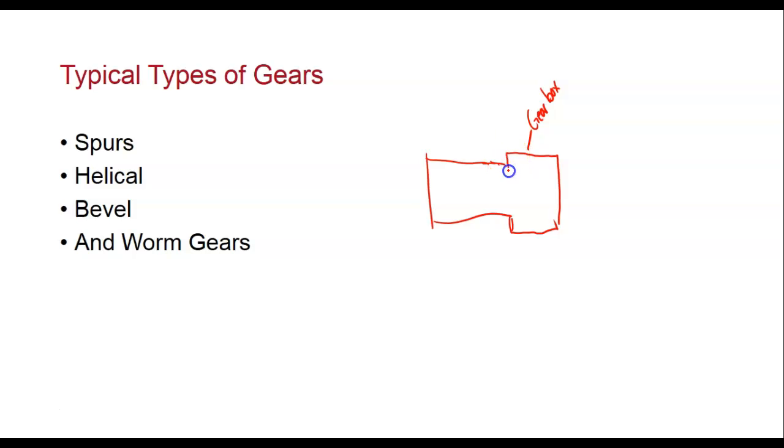When we go over there and look at them, it's got the gear ratio on the front, like 13.5 to 1, or something like that. So it actually tells you the gear ratio between the input and output. These are all the motors that we have on our manufacturing line. So every one of them is a geared motor. Now, how the gears are set up, whether they're spur gears or helical gears or bevel gears or worm gears, we don't know because the actual unit is sealed.